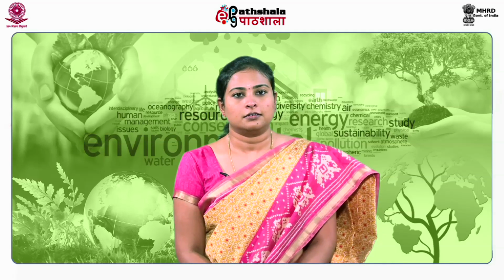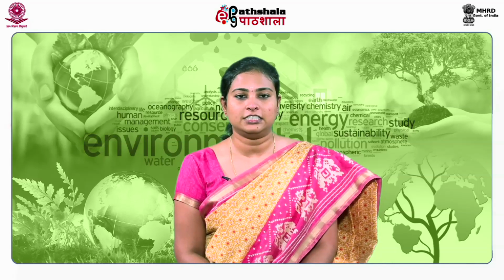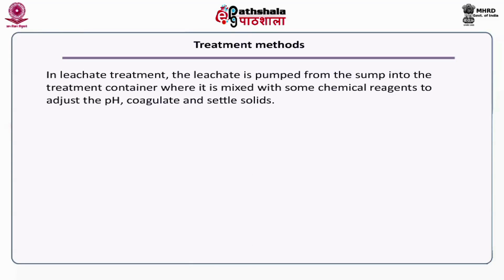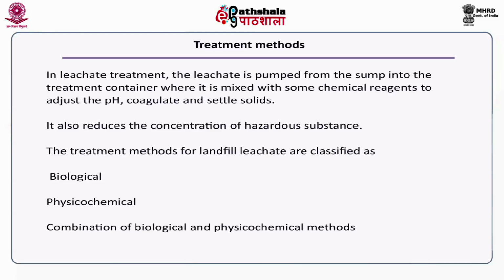Now, with this as a basis, let us look into the various treatment options available for the leachate generated from the various landfills. In leachate treatment, the leachate is pumped from the sump into a treatment container where it is mixed with certain chemical reagents to adjust the pH and to coagulate and settle the solids. By doing so, it will also reduce the concentration of hazardous substances. The treatment methods for landfill leachate are generally classified as biological, physicochemical, and a combination of biological and physicochemical methods. Now, let us look into each of these methods in detail.